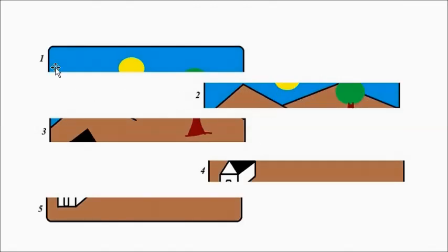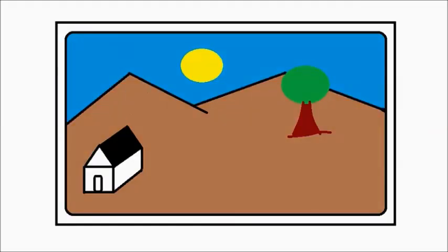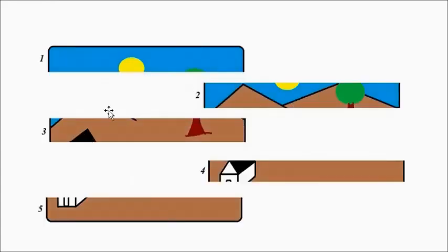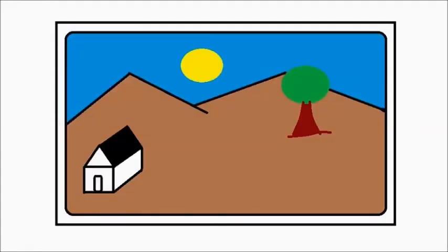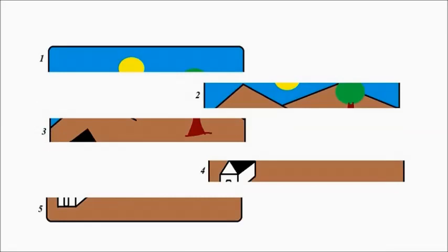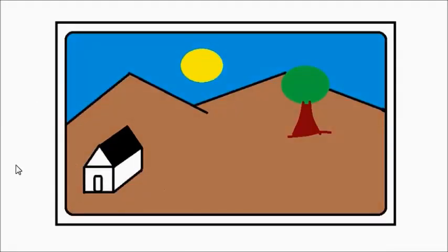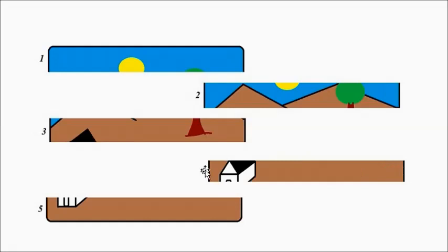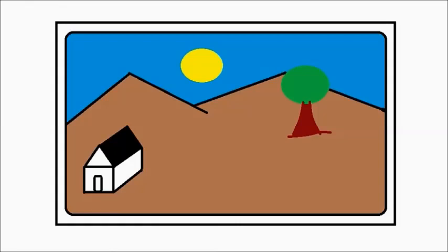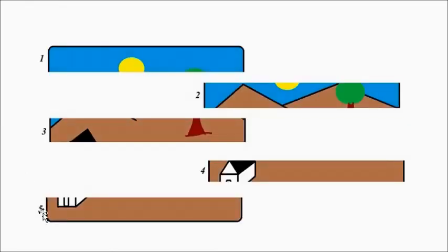Then the portion of the frame below is in the even field. Again the portion below is in the odd field, 3. Again the portion below it is in the even field, 4. And the one at the bottom is again in the odd field. So all these scanning lines lie in between each other, interlaced.